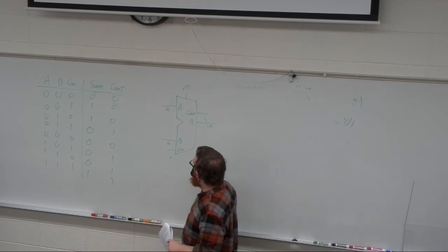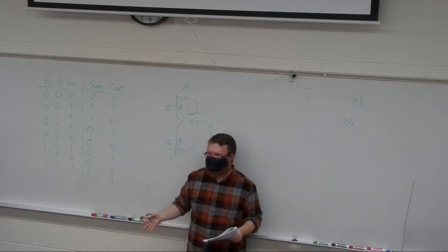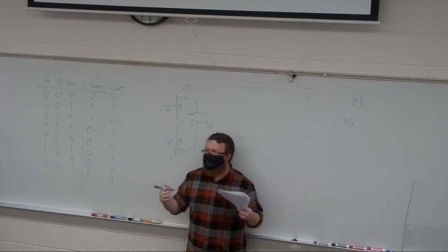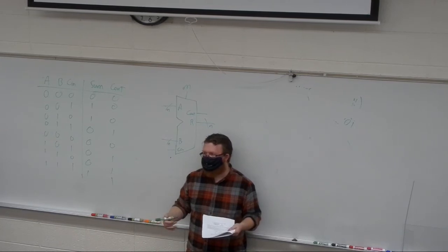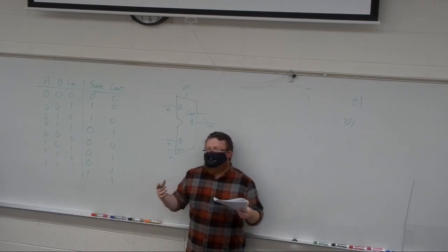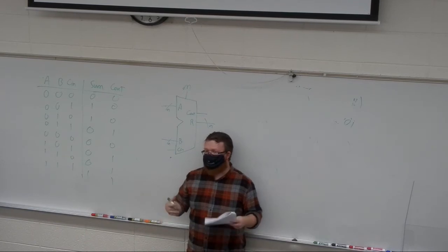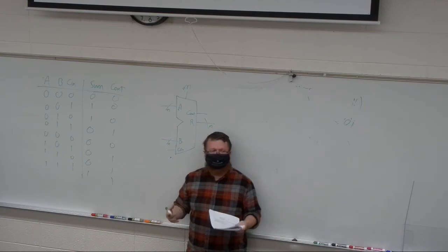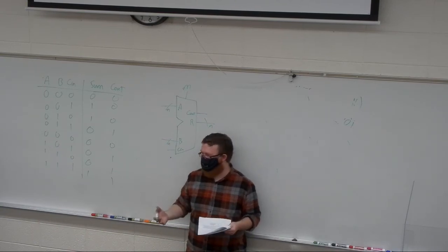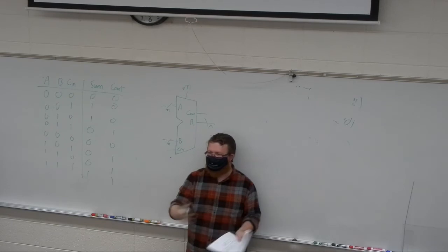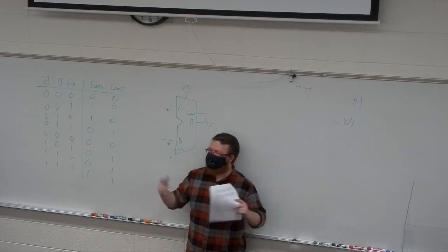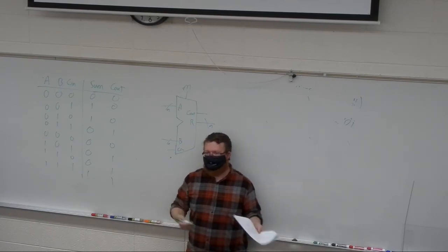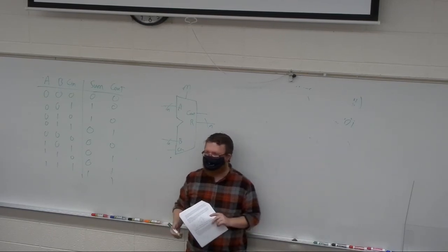It would be difficult to draw gates, right? Because I've drawn the adders, I've drawn subtractors, we've talked about all of this stuff, and it can do all of these operations. What we want to do is build up each of these blocks individually, and then select from the output the proper output. So you can do all of the calculations in parallel, and then just choose which operation you want the output of. What device do we have that allows us to choose one of many inputs?